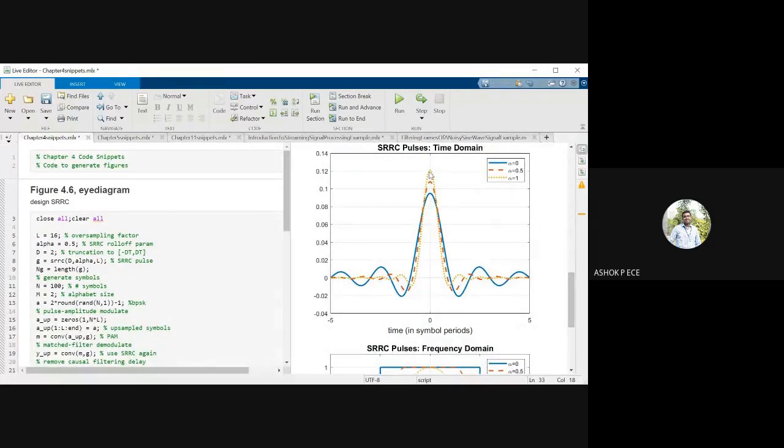See, it is always a cosine pulse. When you put t equal to 0, you will get the maximum value. And from the maximum value, how fast it is falling off is called the roll-off factor. So here, alpha is the roll-off factor, and predominantly we'll take the alpha value to be 0.5.